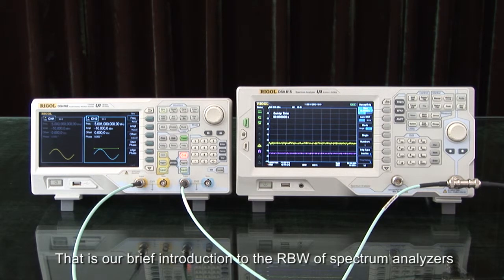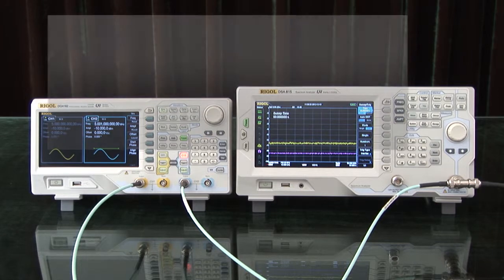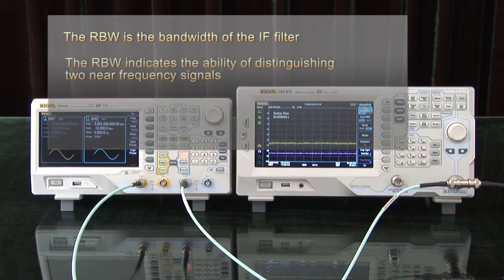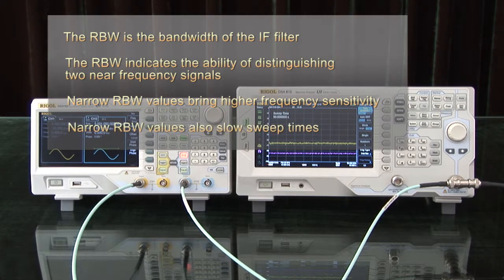This concludes our brief introduction into the resolution bandwidth of spectrum analyzers. Some key points. The RBW is the bandwidth of the intermediate frequency filter. The RBW indicates the ability of distinguishing two near-frequency signals. Narrow RBW values bring higher frequency sensitivity, and narrow RBW values will slow your sweep.